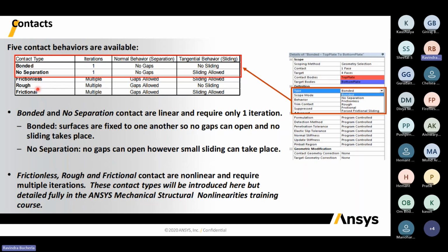So frictionless and frictional are the same. Both will have sliding and separation, but the only difference is that friction will have an additional force which will stop the geometry from moving further based upon the frictional coefficient. For frictionless, the frictional coefficient is 0. In real world applications, most things are frictional. So if you have a frictional coefficient between 0 and 1, you can go with frictional.